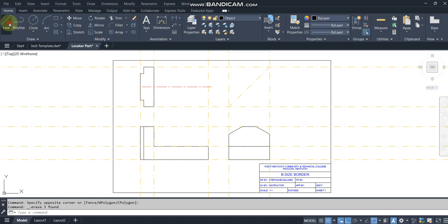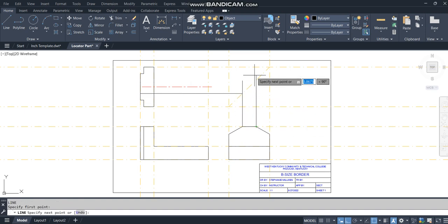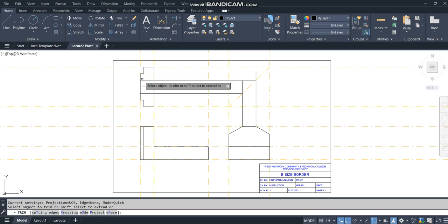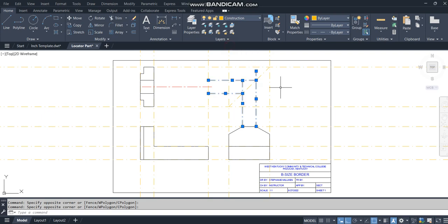Now here's where the miter line comes in. I can project up to the miter line, and then I can project that over into the top view to find that same 1 inch. Now this isn't necessarily required because again, you can use your offset command to figure that out. And then I just trim off the excess pieces. So if I were going to leave these, I'd make sure they were on the construction layer. That way they obviously are not part of the finished product.